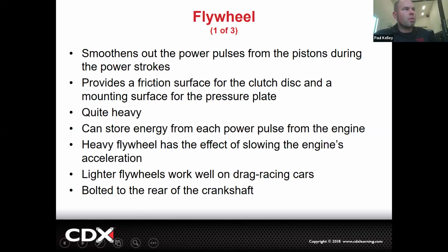The flywheel's heavy on purpose. Do you want a lighter flywheel? Sure, you could put a lighter one. I put a lightweight flywheel on that Civic, and it made it a little more harsh. When we talk about the term NVH, noise, vibration, harshness, when you put a lightweight flywheel on there, it's not smoothing out the power pulses as well. It's not necessarily going to make it vibrate or noisy, but it's going to make harshness.